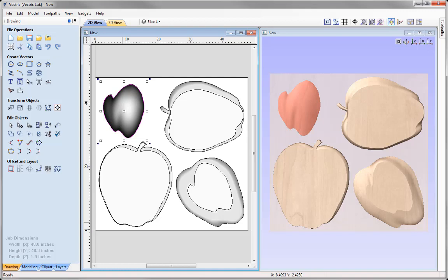And there are a couple of approaches to this. You could add 3D tabs, which you would have to manually remove and clean up, or another way is that we could add a hold down to everything, and it does have its negatives when we come to finishing, and that is to add a thin flat plane that merges through all of the components so that it will stop the roughing and finishing cutting all the way through the part.